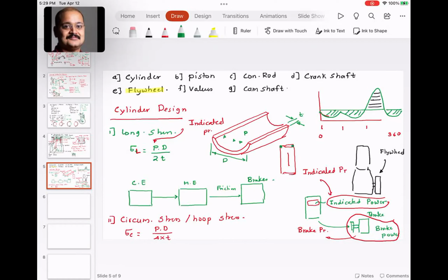I don't know if you know how these soda cans are manufactured. There is something called press tool design. Press tool design means how you take a sheet of metal and design the punch and die, so that when the punch hits the die, you draw the shape that you want. If you look at the soda can from top to bottom, it's just one piece, but the lid is actually put on it. So it is actually crimped, and sometimes, depending upon the pressures that you use, it could be fused.